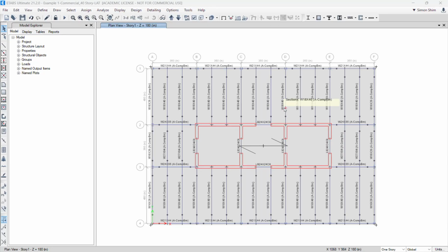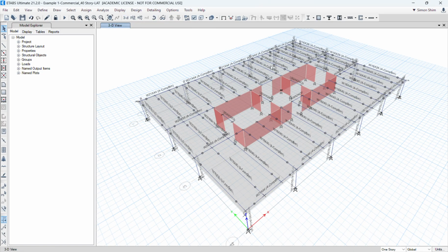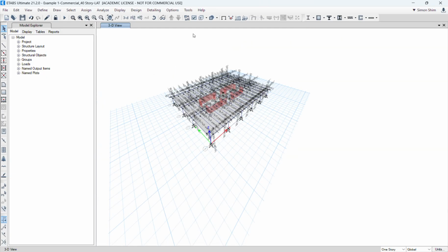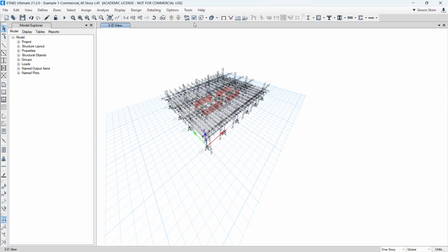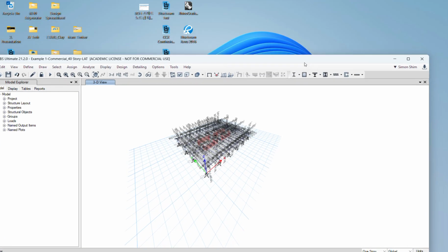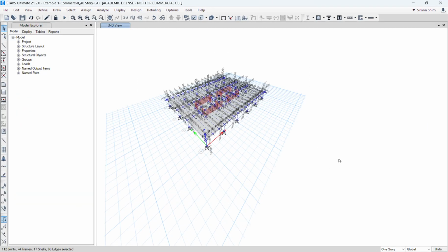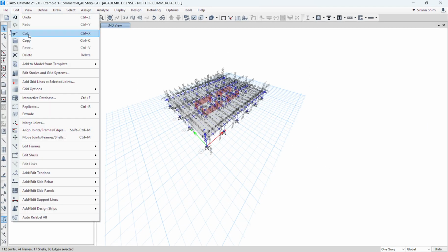All right, next step, since the model is ready. The composite beam design is completed. The wall we initially set up with the link beam is ready, and we are ready to copy it. If you want, you could just assign the diaphragm earlier, but it's up to you. So first of all, I'm going to select and go to Edit and Replicate.